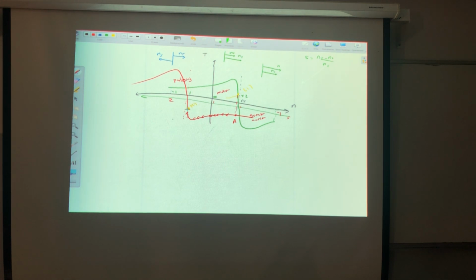Now the dynamic braking for the induction machine is slightly different from the DC machine. In the dynamic braking, what will we do? For the dynamic braking, I will disconnect the terminals of the stator. If I disconnect the terminals of the stator, the machine will be what? Free run. Yeah? But I need to brake it.